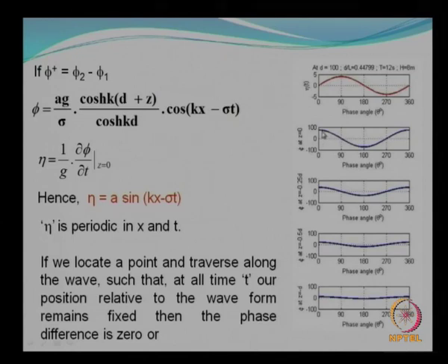So this is at the still water, and slightly below it, that is 25% of the water depth, and this gives the variation of the magnitude which is less than at the still water line. Now at a distance of about 50% of the water depth below the still water line, you see that the velocity potential further reduces. So you see the phase variation and how the velocity potential reduces as you go towards the seabed.